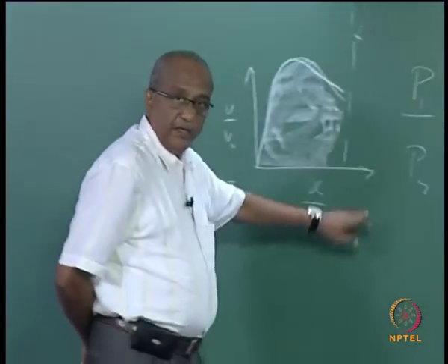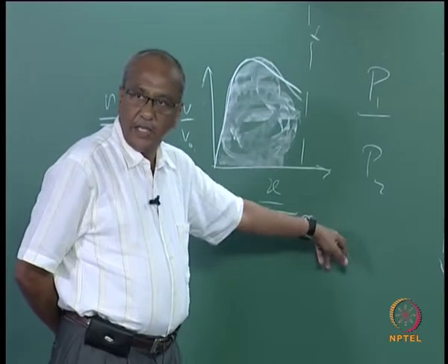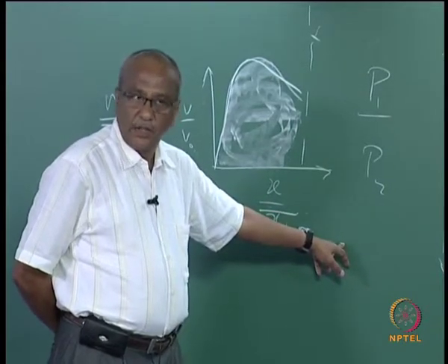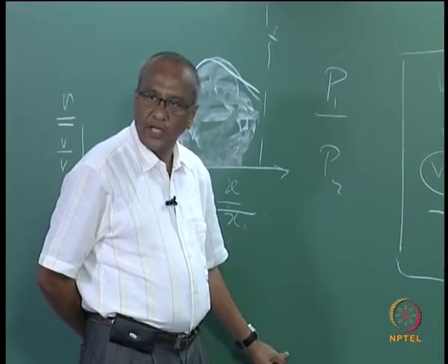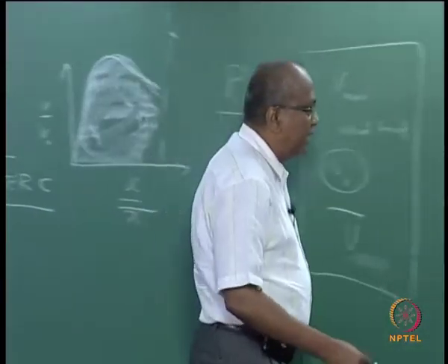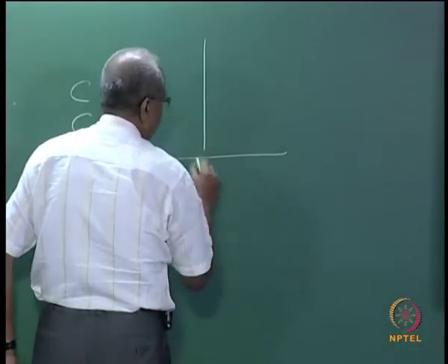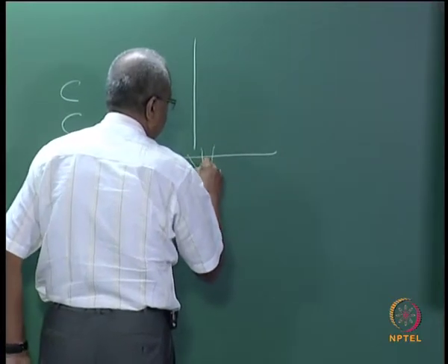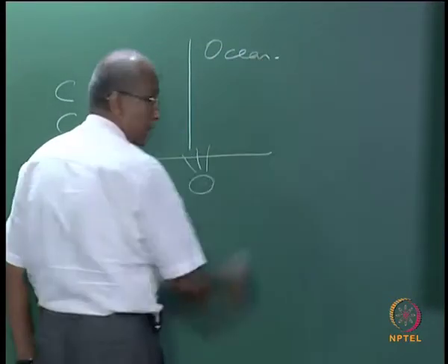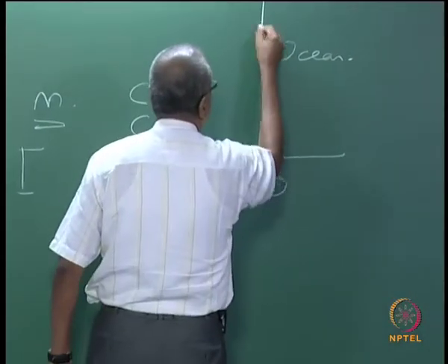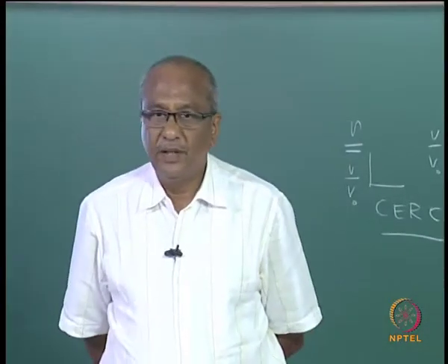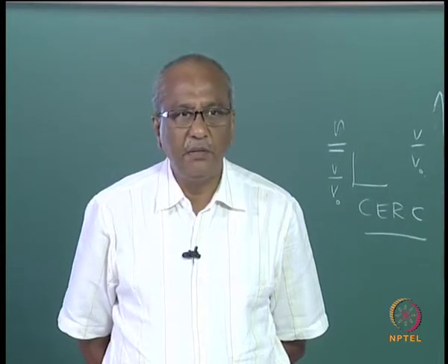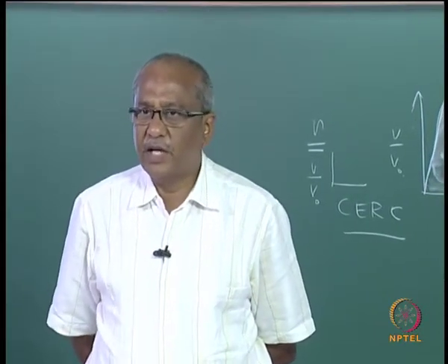That is true, no? Because the Longshore current velocity, as I have said, is because of the oblique attack of the waves. So the greater the angle, the greater will be the Longshore current velocity. Again to recollect, when you stand here and look into the ocean, if you see that the waves at a particular location are approaching normal to the shore, what does it mean? You do not have a Longshore current velocity at all.